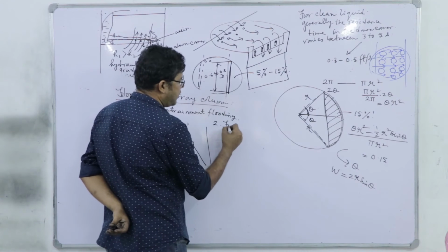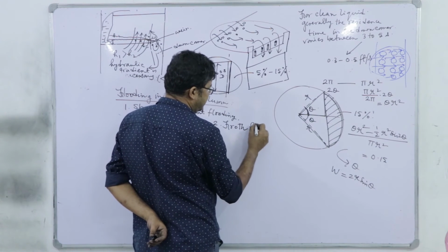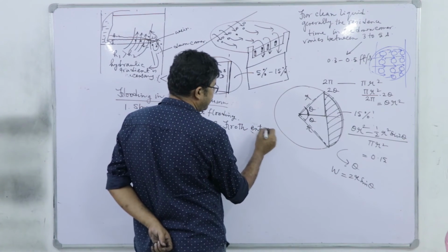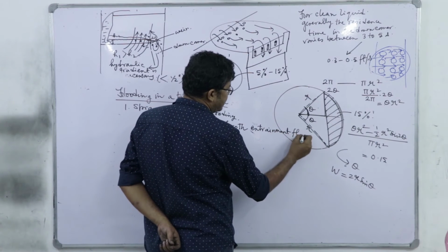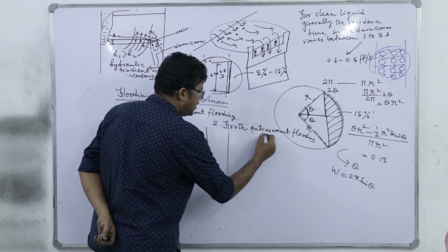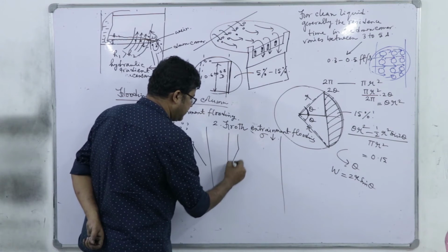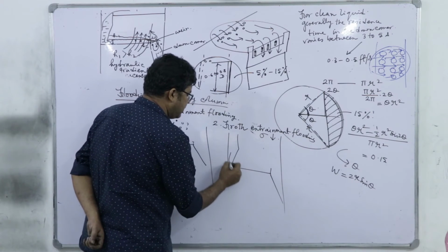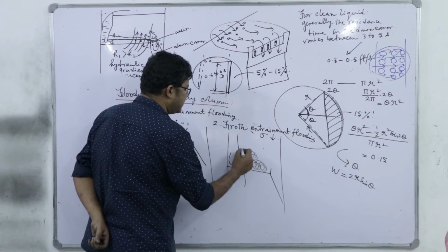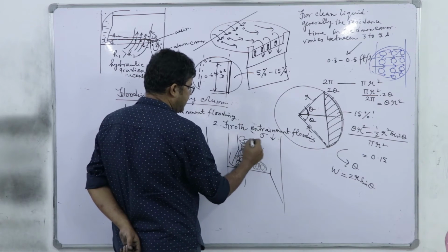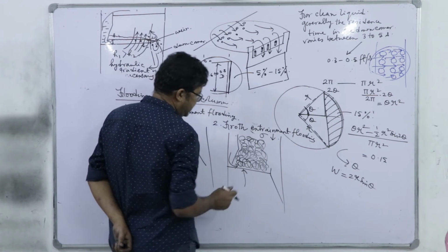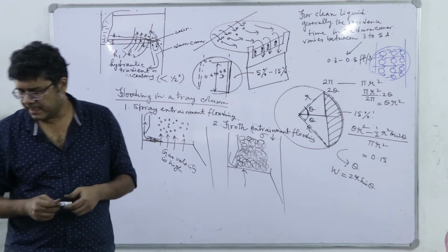Second, froth flooding, froth entrainment, or what is the exact name? Yeah, froth entrainment flooding. Here we have a low surface tension, or rather low interfacial tension between the liquid and gas, and when the liquid flows, the gas having contact, it forms froth, and the froth grows in size, it entraps the liquid in it, and finally, in case of extreme feature, it may percolate into the tray above, right. So, this is the froth entrainment flooding.